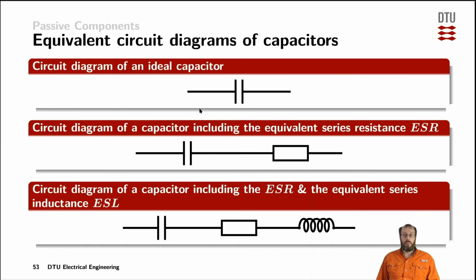The electrical symbol of an ideal capacitor looks like that. But you can never get a capacitor without having the leads connecting the plates to the rest of the circuit, which are actually representing an extra resistivity. And that extra resistor is then also representing another inductor, because there would always be a magnetic field around any